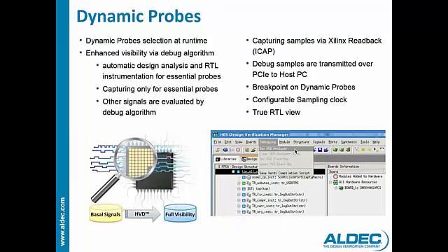So in order to look for a breakpoint, the data needs to be sent to the host. Hence, it's a slow process. You have to specify the time in which to check for the breakpoint, for example, checking for a breakpoint condition every 1,000 clock cycles. This type of breakpoint can be useful for slow changing signals, but not for fast ones.